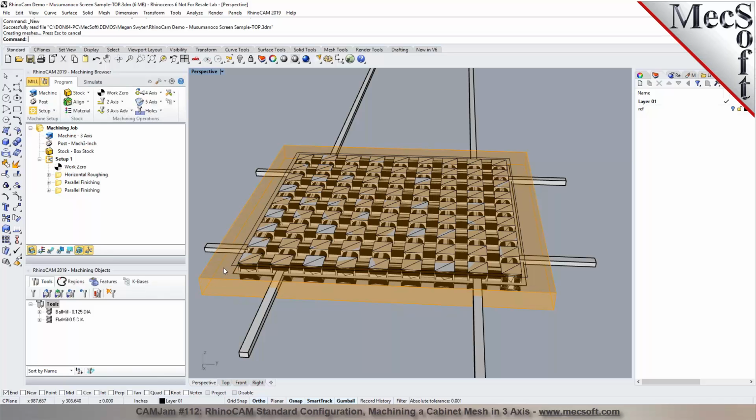In other words, you need to know where to put your holes to mount this. But depending on your geometry, you need the stock to be symmetrical with the part and the part centered, so that in this particular part, all you have to do is flip it over. When you flip it, it'll be exactly lined up.